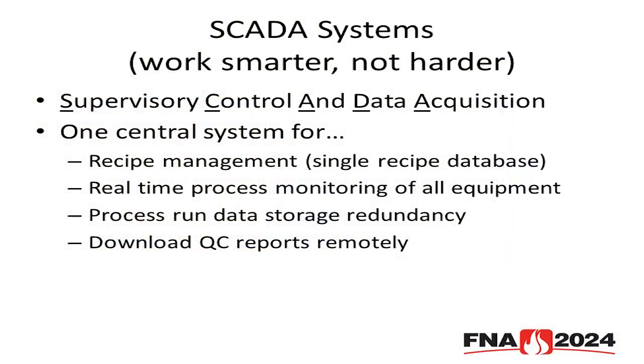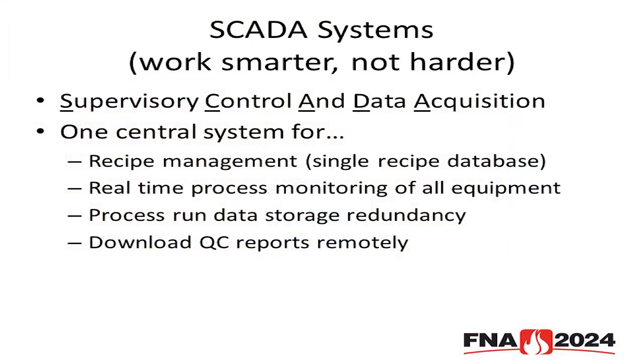So one of the biggest advantages is a single database for all of your recipes. So if you've got 10 furnaces or 12 furnaces or 15 furnaces, and you spend a lot of time going to each furnace and making changes to recipes, and then you're not sure, a couple of years pass, and this one has a slightly different version of the recipe than this one over here, and you're constantly doing all these edits, this is one of the places that a SCADA system really shines because we have one central database for all our recipes. So you make a change in that database, and it pulls to all the furnaces. So when that furnace goes to load the recipe, it's just pulling from that one database, and you don't have different versions of the recipe.